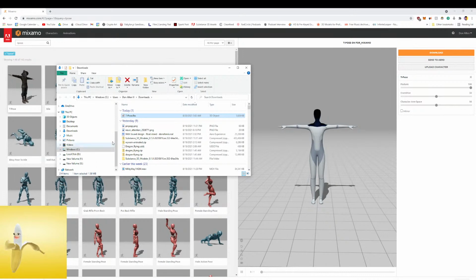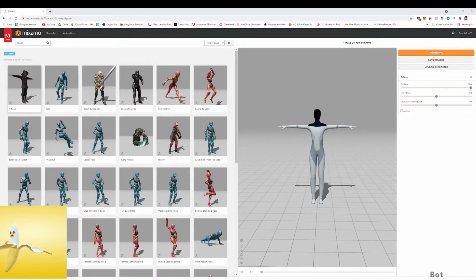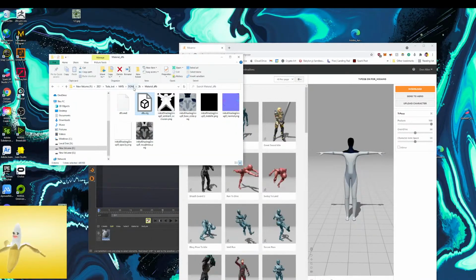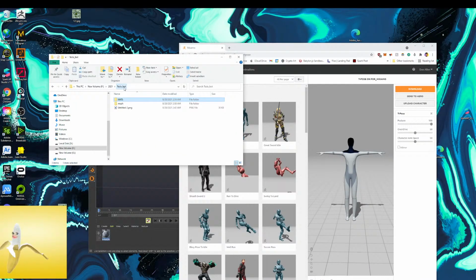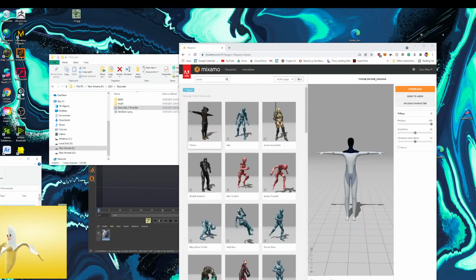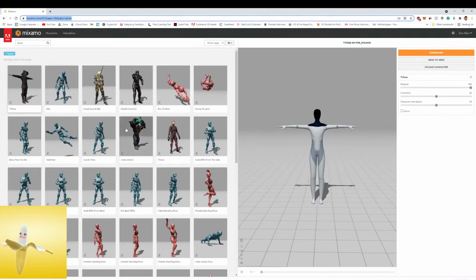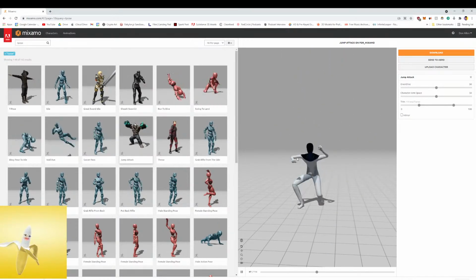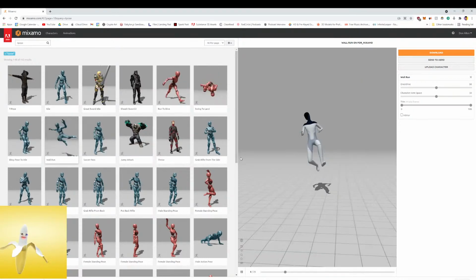And I just saved that T-pose in a good spot. I'm gonna rename it Tesla_bot_T-pose. And the reason why we want that T-pose is it's rigged and it gives you a lot of flexibility to really do anything. You can model the character however you want. You could repose it later on. I always try to get that data out. So I just got my T-pose, and then everything else after that is just icing on the cake. If we want to add some little animations, oh, that's kind of fun.